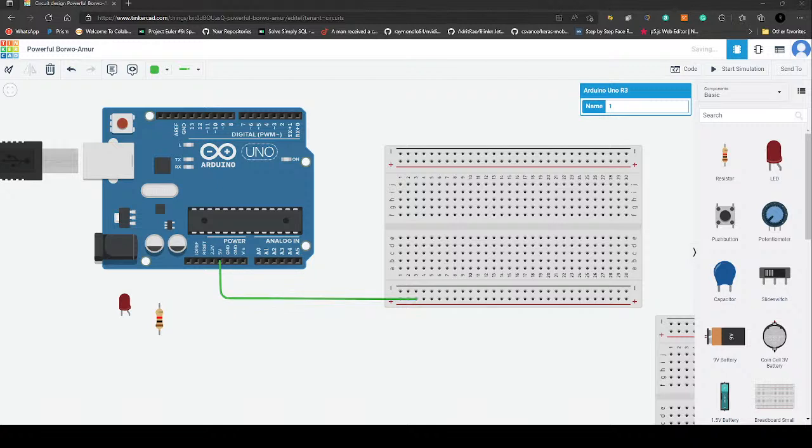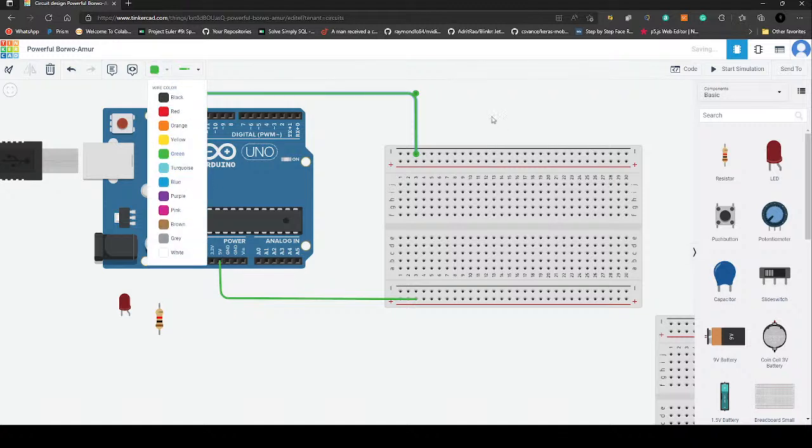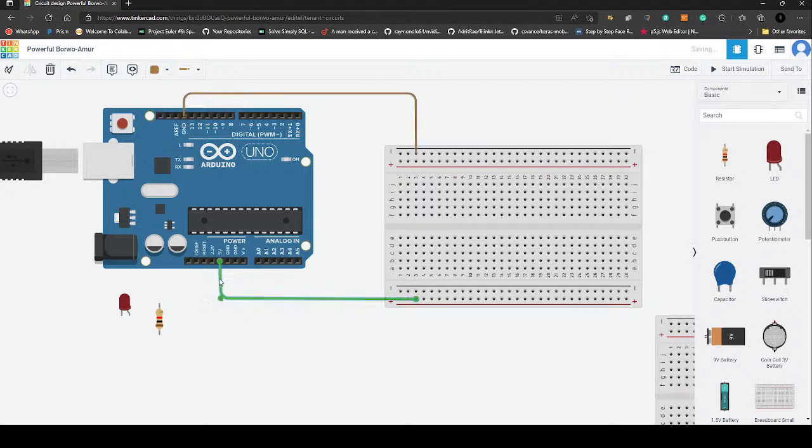So first we will connect 5 volt, and this line, as you know, this line is connected to the ground or minus, which I said, to the other pin. It is always a good practice to change colors, like for ground brown and for VCC or 5 volt keep red. We need to connect a LED. So you know this is connected vertically.